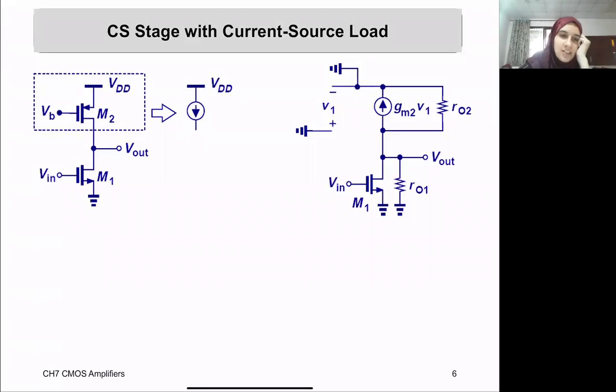Mostly, there are not many downsides. It's a good thing that we want to do. As you mentioned, we get a high output impedance, and the voltage drop across it is not related to the value of the impedance, so they are not proportional to each other. So I'm not at risk of leaving the saturation region, and I also don't use much chip area.